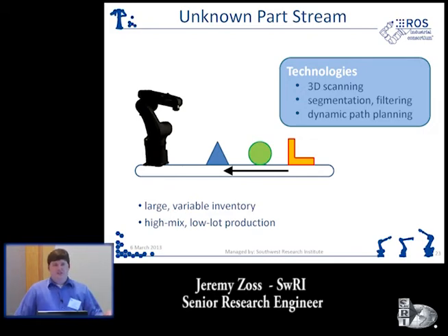We've talked about the 3D sensing. You can scan the part. You can build up a knowledge of what that part looks like and then build your process path to do a raster scan or edge following or find key features for inspection. And all that stuff is generated on the fly for the robot to execute. So that would be a difficult problem to solve with a traditional robot controller, but the flexibility of the path planning and the sensing in ROS is well suited for unknown incoming parts. Similar to that is bin picking.